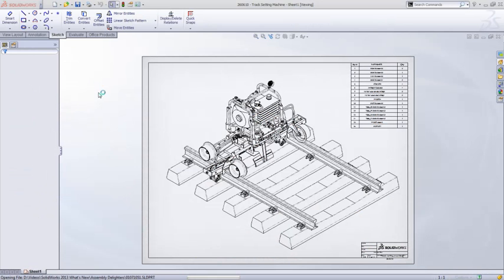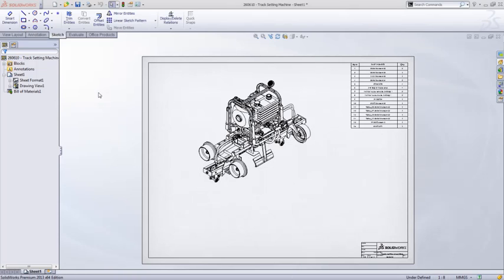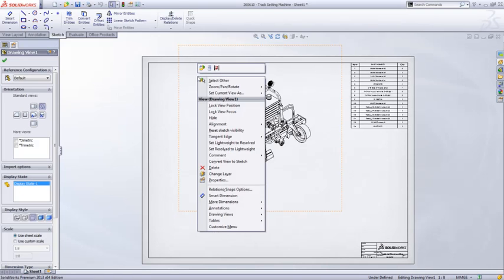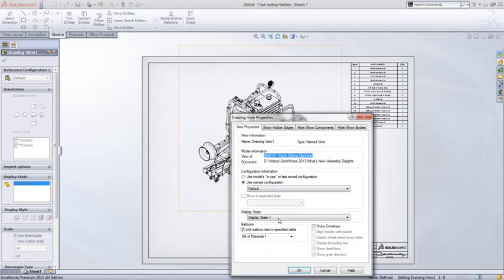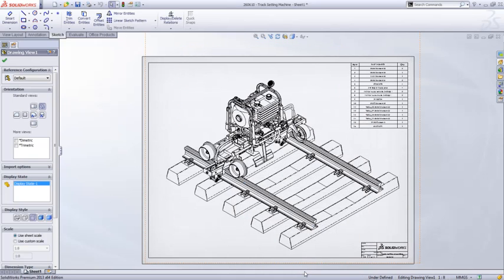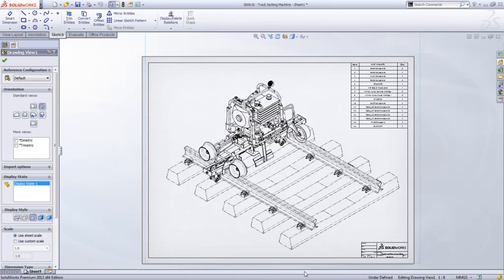For example, if we open a drawing containing this, it's immediately removed from the bill of material and the view. If we would like to show this reference geometry, we can choose any view and opt to enable the Show Envelope option. Any envelope components will be immediately displayed with the unique phantom line type.